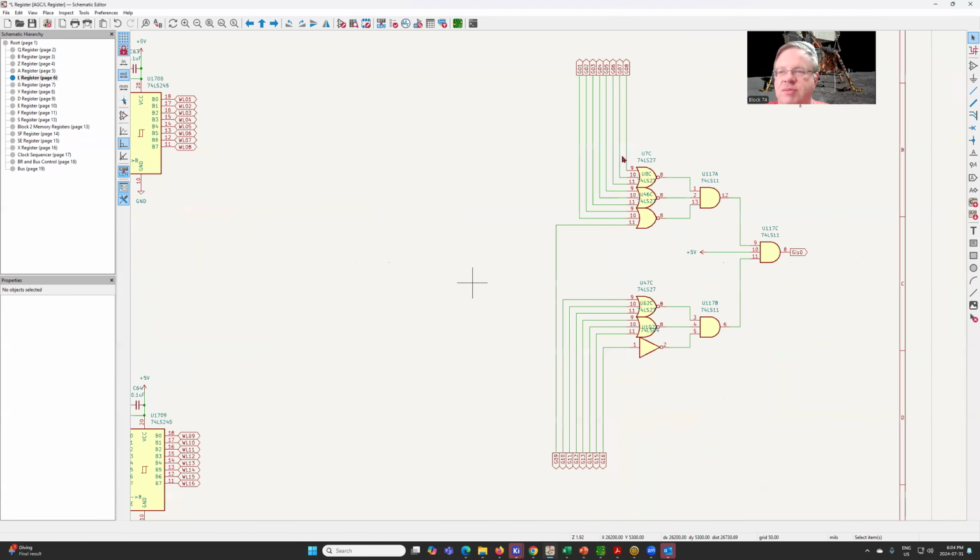And one of them is a test to see if the contents of G are 0. So what I'm going to do, because I have G on this board, is create a little bit of a logic tree that will basically do the test to say, is G 0? Then I can use this for some of the test logic, so that on the test board, if I get the control pulse that says, are we checking to see if G is 0, this kind of logic will be available on the backplane for us to validate